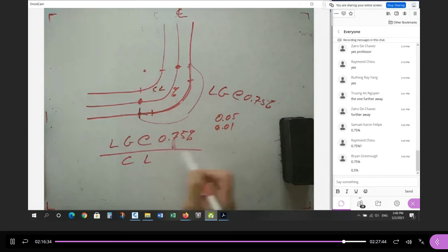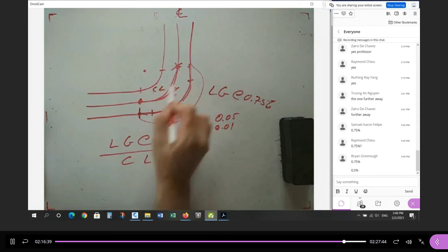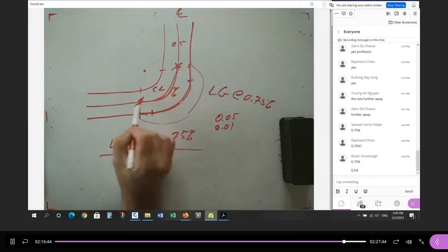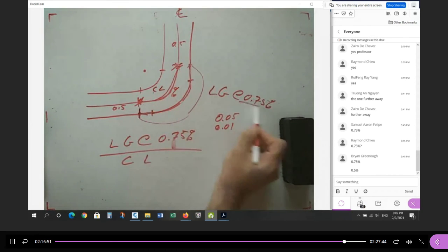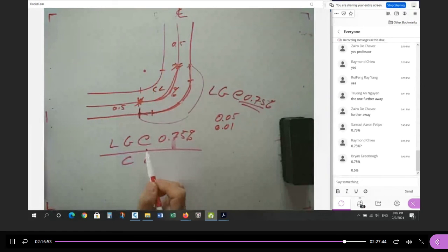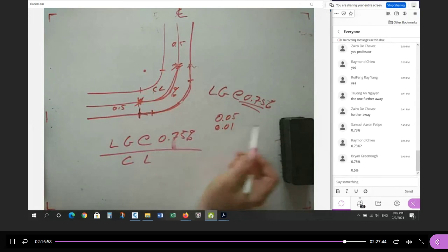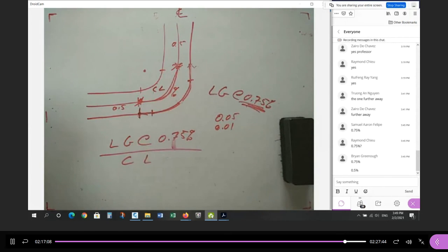Always round it up. So make whatever you calculate, round it up to a nice clean number for the slope. So this point and this point are going to be 2 points on your profile where the slope is not 0.5%. On the straightaways, it's 0.5%. On the straightaway, it's 0.5%. Between these 2 points, it has to be a little steeper so that you guarantee the minimum gutter grade on the outside curve. This discussion is exactly the same. The geometry is different. The standard slope is different. But the procedure is exactly the same. So I'm just telling you this as a reminder. You have to figure out what that center line slope is.